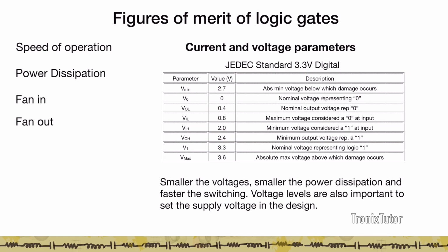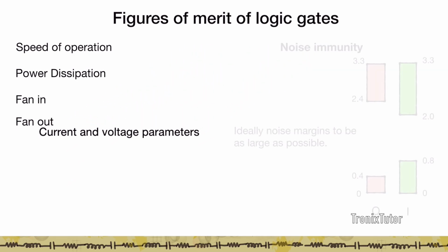So that's something you need to keep in mind when you're picking the right voltage levels. These voltage levels also determine the kind of device you're going to use in the technology, because the voltage level determines the supply voltage, which tells you the maximum voltage a node can have in the technology, and also tells you what is the largest field. So when you're designing a semiconductor device, this limits the size of the device.